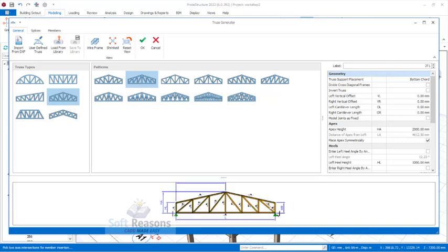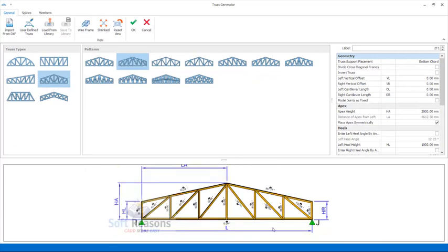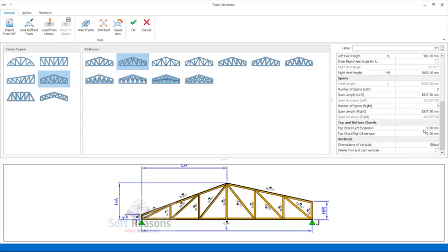Okay, so having picked that type of truss, what we will now proceed to do is to carry out the settings. So if we check the apex height is 2 meters right there. And then the left ear is 1000. So here we change it to 300. So we click in that provisions. All right, we navigate down to the right here, and then 300 again.